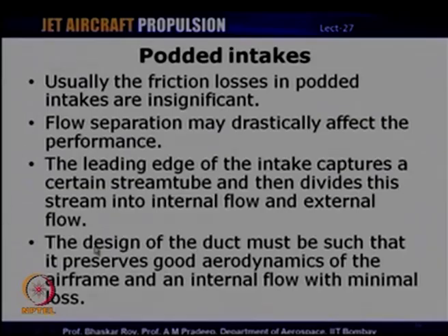And whatever be the geometry, whether it is podded or flush or integrated intake, the duct design also plays a significant role besides just the leading edge of the intake. The design of the duct should be such that it preserves the good aerodynamics of the airframe.